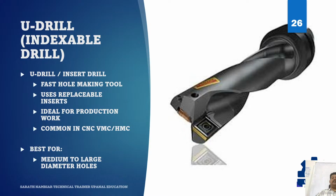Secondly, U drills are designed for faster drilling of large diameter holes. Third, they are common in CNC machining centers where repeated hole making is required. If a job contains many holes of the same size, your U drill can become a productivity champion. Now, does it replace all drills? No. Small holes and certain precise jobs may still use conventional drills, but for production hole making, especially medium and large diameters, U drills are extremely valuable. And when students learn the U drill, they step into modern CNC thinking.